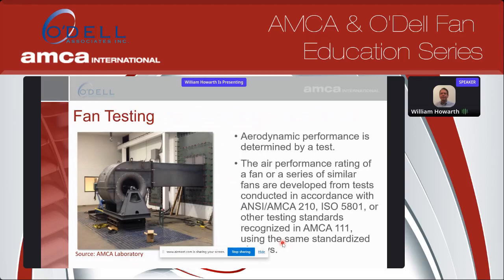Well, that fan curve is produced by an aerodynamic test. How much air and pressure the fan delivers is going to be established by a test. And this is a picture of a fan in test at the AMCA laboratory in Arlington Heights. The fan here is tested with an open inlet. You can see the inlet of the fan right here, and a ducted outlet into the test chamber. The AMCA lab is an A2LA accredited lab and is recognized by the National Institute of Standards and Technology.